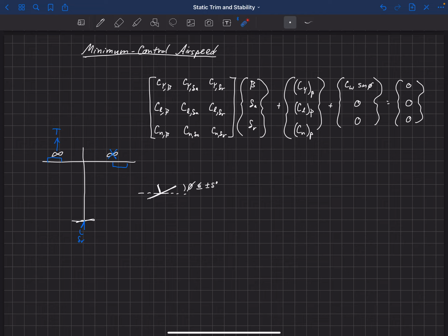So anyway, this whole phenomenon here, this engine out scenario, is one of the main reasons why regulatory agencies require a separate pilot's license for operating a multi-engine aircraft instead of a single-engine aircraft. Now, you can still have similar effects with a single engine, but they're not nearly as pronounced as they are on multi-engine aircraft, where your asymmetric forces and moments are extreme. They're very large if you lose an engine.